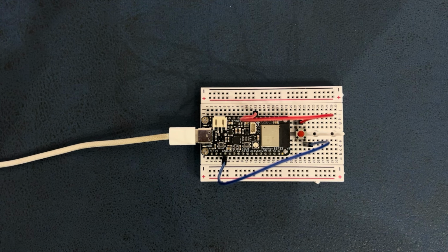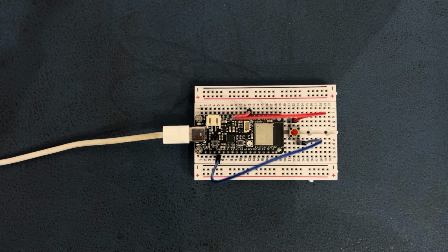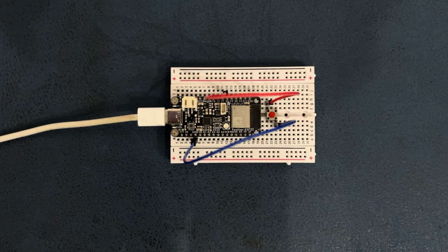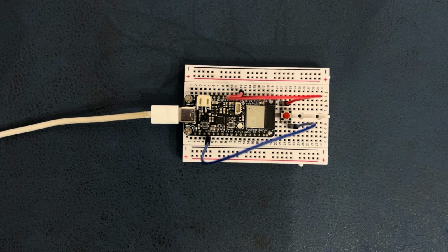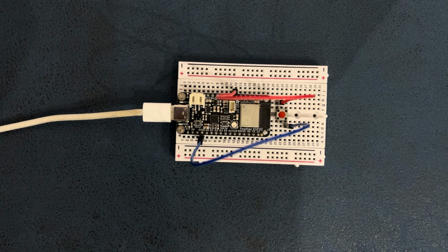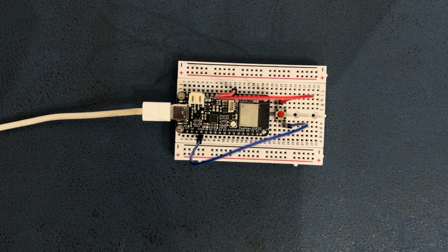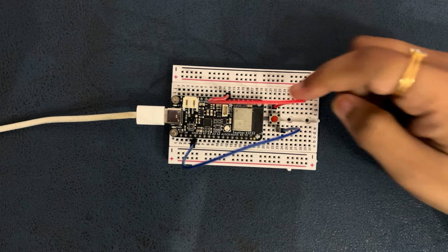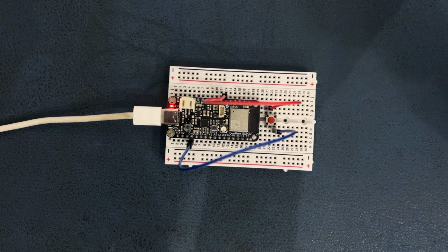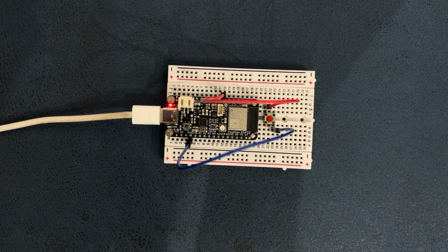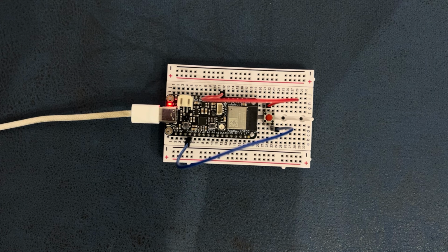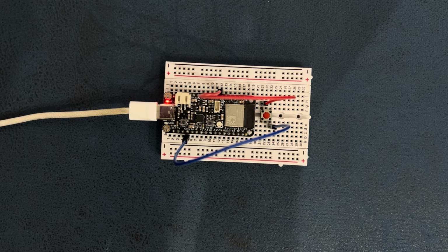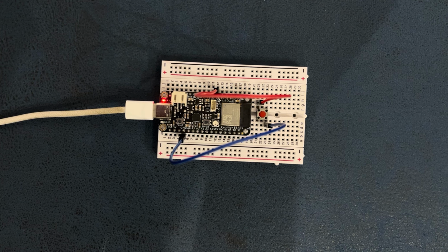So hence, for wake up demonstrations, there are two ways. The board wakes up when the timer expires. After 1 minute, the board wakes up automatically and the shell shows woke up due to timer wake up. And the other way is the external wake up button press. If I press the button during sleep, it wakes up immediately. The shell will show woke up due to external wake up. After wake up, the entire process repeats. Wi-Fi is connected, NTP is synchronized, touch recalibrates, timers restarted.